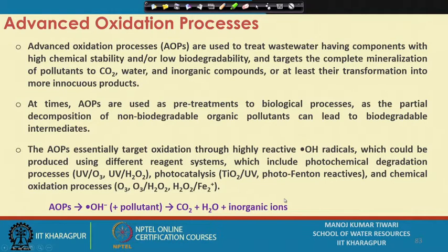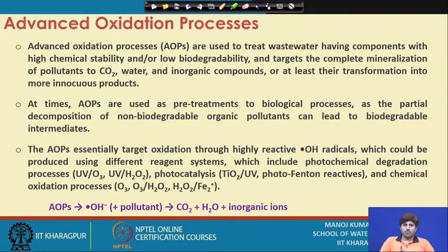Then there are advanced oxidation processes also, which target the removal of various compounds which have higher chemical stability or low biodegradability. So, the refractory organic compounds which we discussed can be removed through adsorption or those kind of things. Adsorption is a process of removal or phasing them out of water, but advanced oxidation processes are the ones where they can be decomposed and degraded to non-toxic elements.